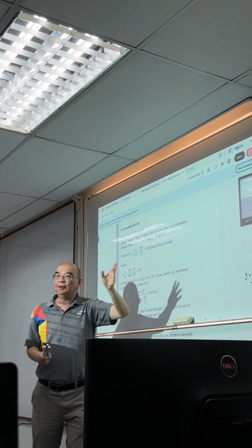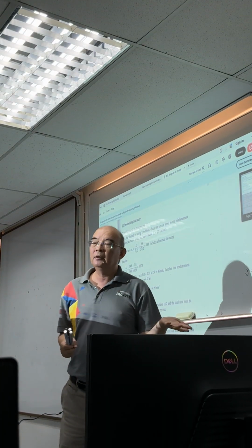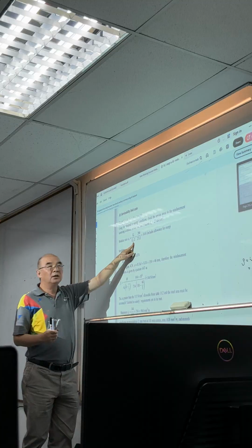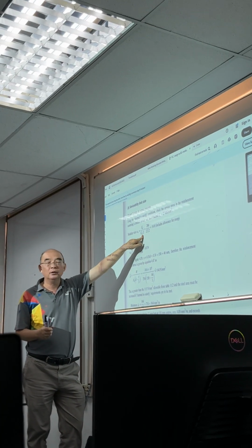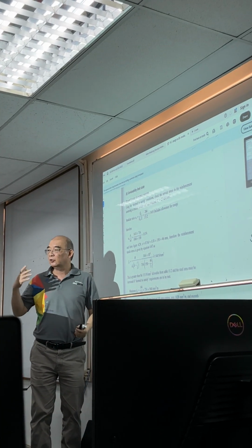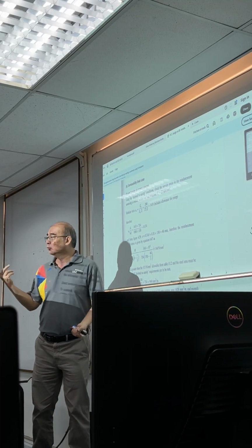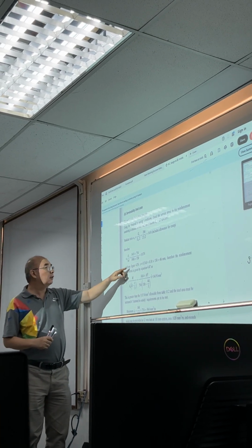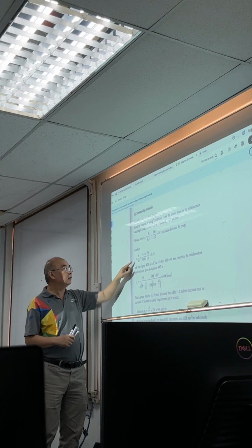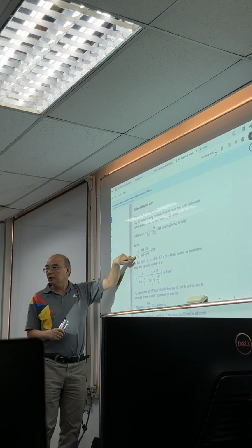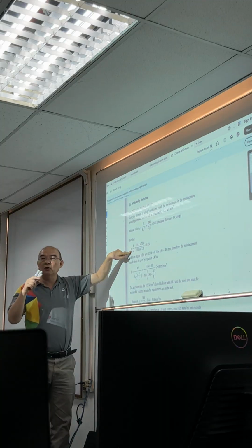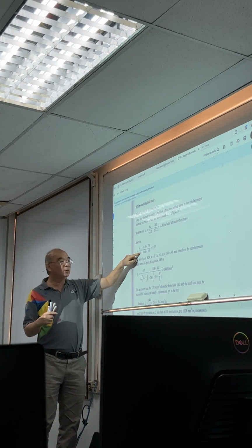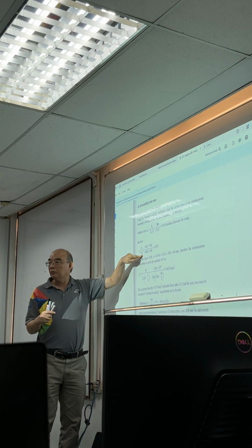In test 2, I will give these values to you, so you don't have to worry about it. But you should understand why we divided by 2, because the creep coefficient is roughly 2. So here he calculates the 14.8, which is alpha C. In the book, they call it the alpha C. Then what is this one? This is N rho.